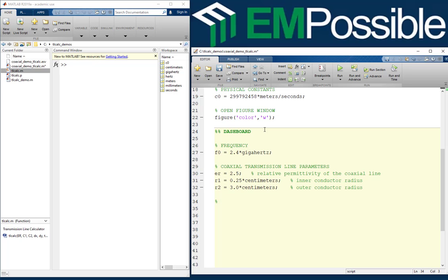Now let's define some grid parameters. The first one is what I call nres, and this is going to be our grid resolution. This is the number of points or cells that MATLAB will resolve per length that we will choose later. A higher nres means a higher resolution simulation, which can lead to better or converged results, but also it can make your simulation run slower.